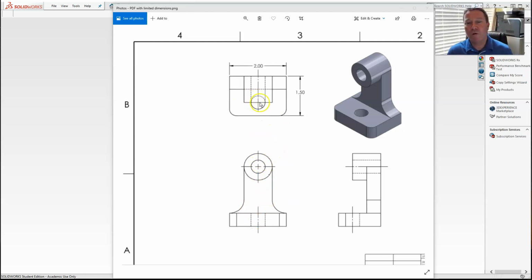Similarly, if you trace around a hole and get a dimension close to a half inch but not exactly, make it a half inch. You can make the assumption that that was the design intent. Does that work every time? No, but in our simple parts, for the most part, it will work.